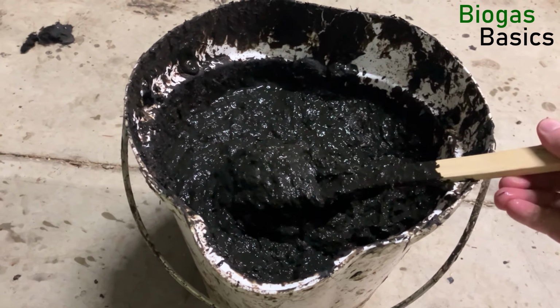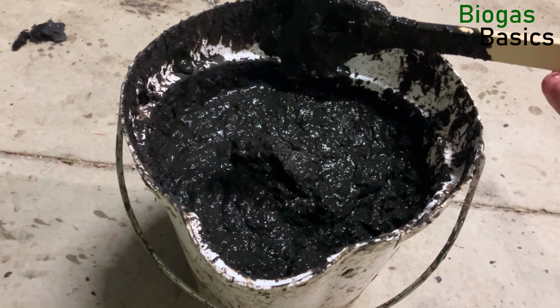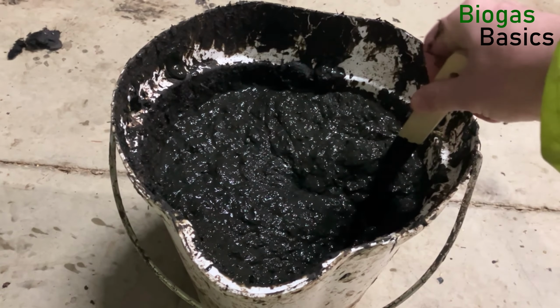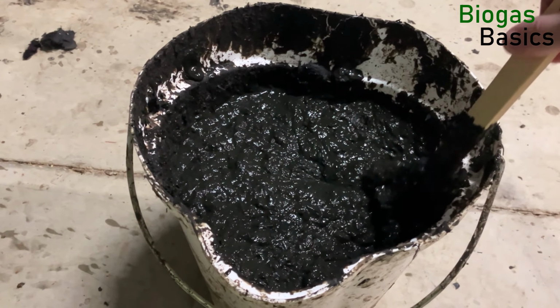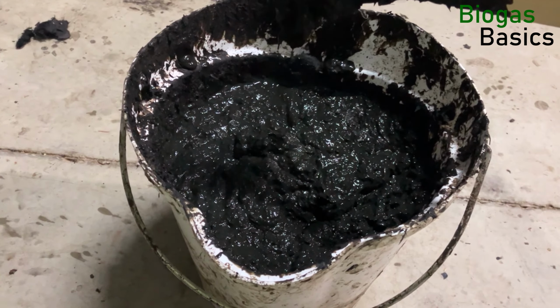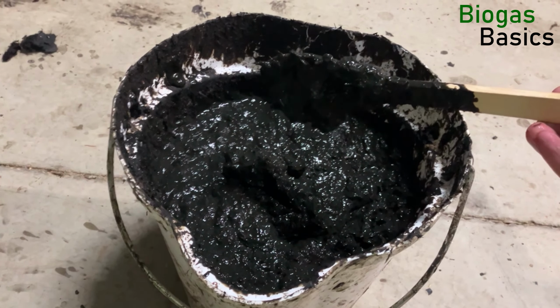Digestates in dry fermentation are characterized by a noticeable yield stress. They do not show the hydrostatic stress state, which is defined by a tensor with only normal tensions of equal size and leads to flat surfaces in resting fluids. A non-moving fluid with yield stress can sustain shear stress, so it can show an uneven surface. The first presentation in the mini-series about mixing, presentation 12.1, will explain dry fermentation in more detail.